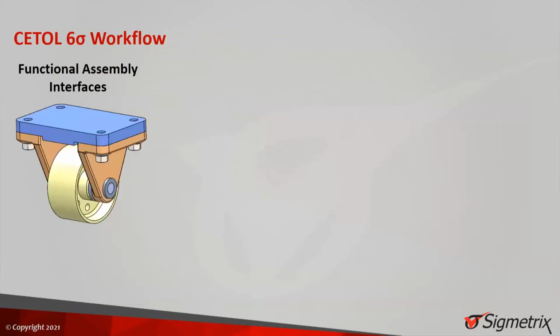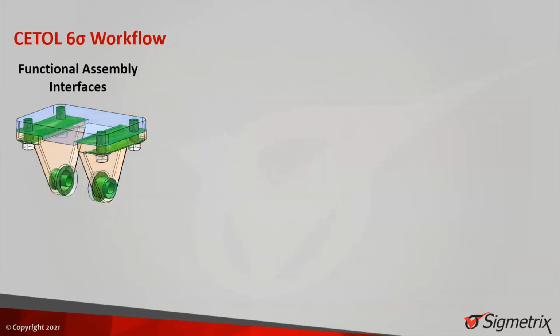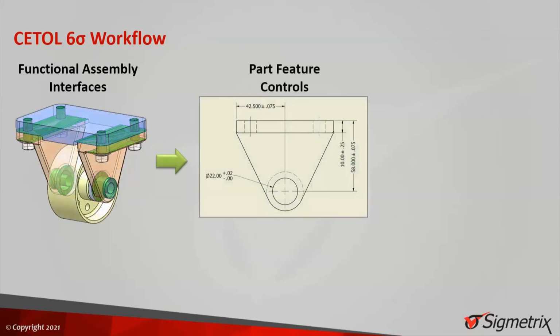So what is the 3D stack-up? Firstly, you got the 3D CAD model, right? Even in concept design, you got the critical functional assembly interface. You can also use this tool to do the stack-up. But in that stage, we usually do the sensitivity analysis. Going to the second stage, you got some drawings or you have to do the tolerance design, so you have to determine the tolerance values.